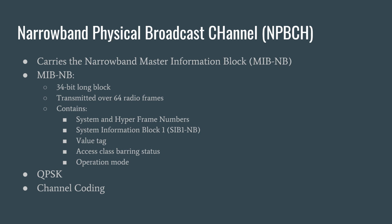The MIB-NB contains key information, including the system and hyperframe numbers, the System Information Block 1, or SIB1-NB, scheduling and size, the value tag, the access class barring status, and the operation mode. There is also some reserved space for future use. NPBCH uses QPSK, and the channel coding process is very similar to what is used in conventional LTE.